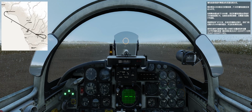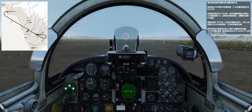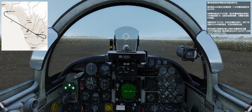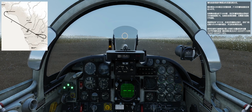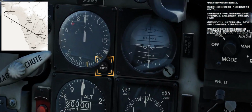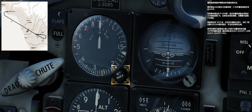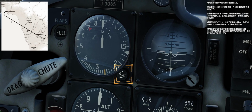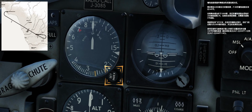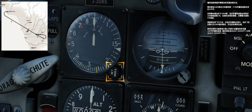The landing speed is calculated based on the remaining amount of fuel and armament. With 1,000 pounds of remaining fuel and no armament, the landing speed of the F5E is 145 knots. If remaining fuel is more than 1,000 pounds, your approach and landing speed must be increased by 1 knot per 200 pounds over. If the guns have a full ammunition load, you need to increase the speed for another 5 knots. According to estimations based on flight plan, during the approach and landing, your aircraft will have approximately 1,000 pounds of fuel and full gun ammunition.